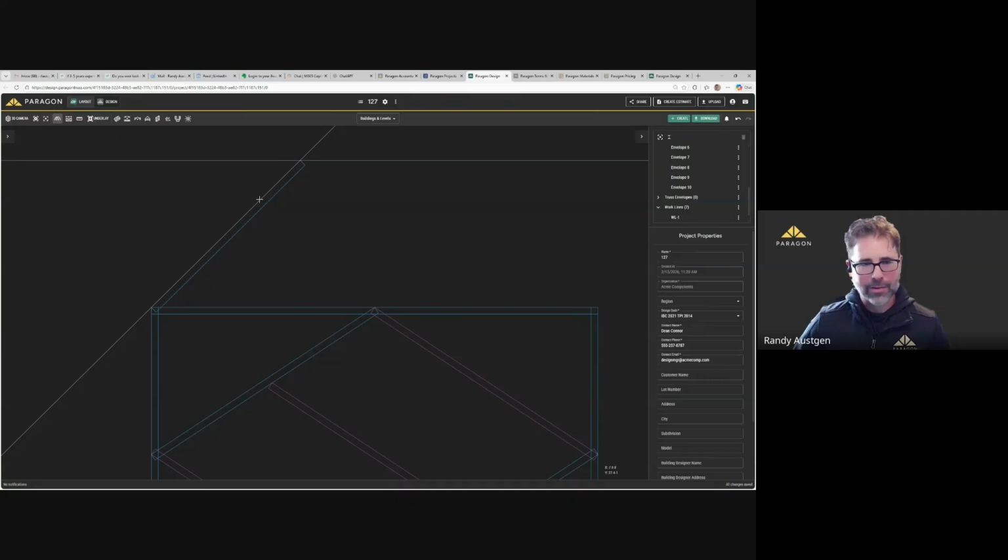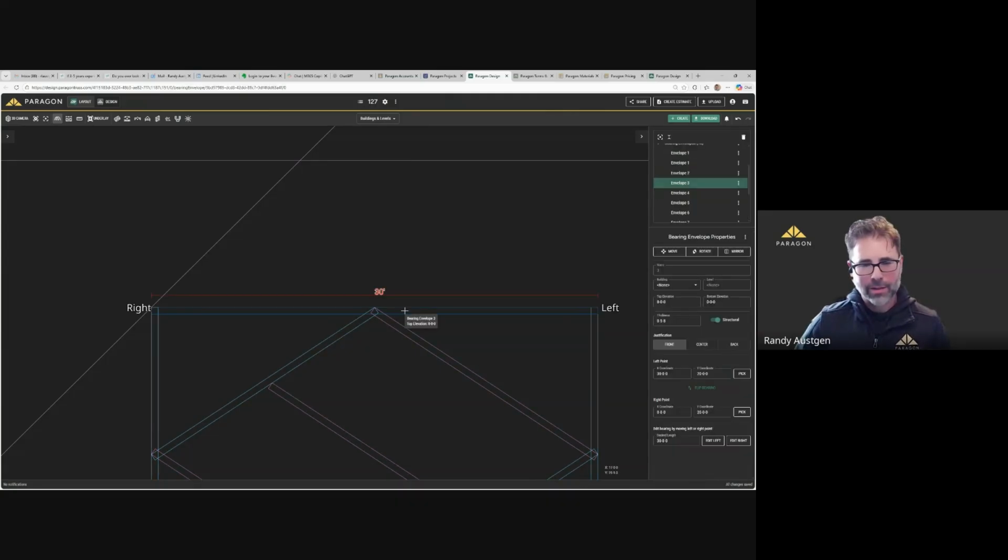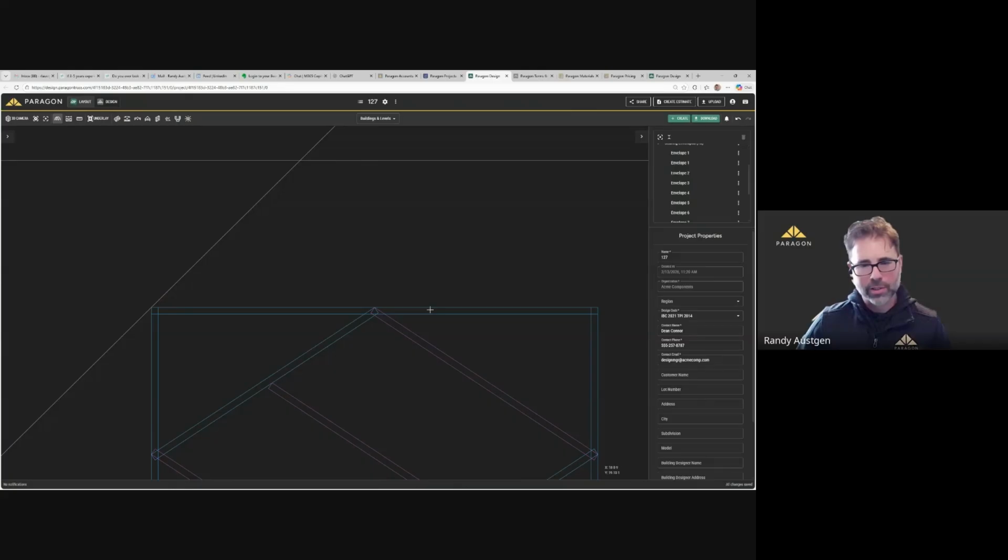I'm actually going to help answer I think that was Lane's question. I'm going to answer that while I do this. So if there's a bay window coming off of here, say 2 feet up, what you could do is draw in another wall up here at 2 feet, and then your distance over, and then you could just connect those points.